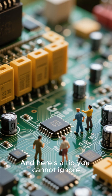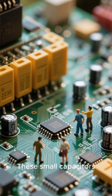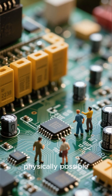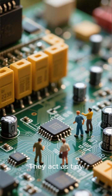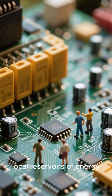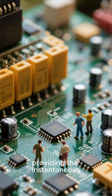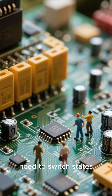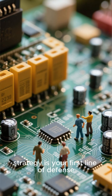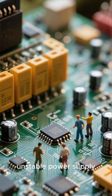And here's a tip you cannot ignore: decoupling capacitors. These small capacitors must be placed as close as physically possible to the power pins of every single integrated circuit. They act as tiny local reservoirs of energy, filtering out high-frequency noise and providing the instantaneous current that chips need to switch states. A good decoupling strategy is your first line of defense against a noisy, unstable power supply.